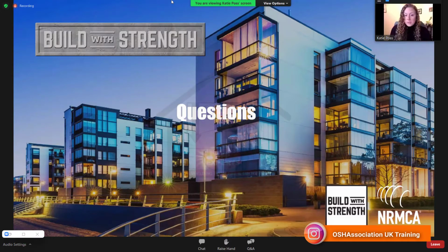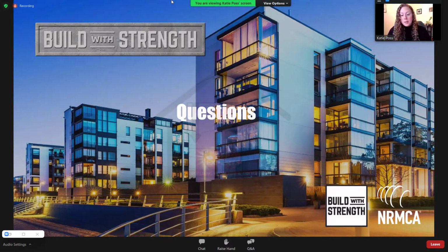Yeah, that's a good question. I mean, you can certainly use the Athena Impact Estimator if you're familiar with it. Agreed that some of those tools are complex. There are also other whole building LCA tools like One-Click LCA and Tally. You could certainly use the EC3 tool if you know your product-specific EPD for your mix to calculate just concrete.